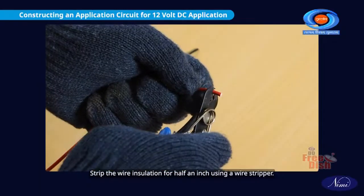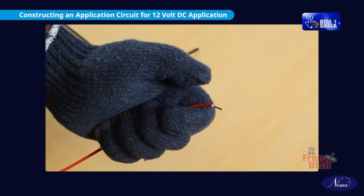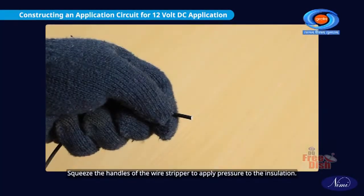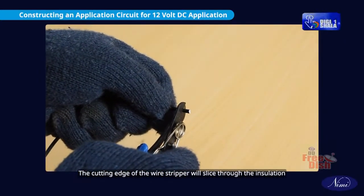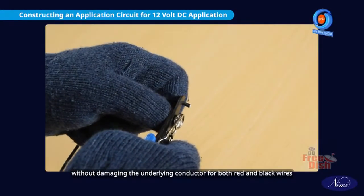Strip the wire insulation for half an inch using a wire stripper. Squeeze the handles of the wire stripper to apply pressure to the insulation. The cutting edge of the wire stripper will slice through the insulation without damaging the underlying conductor, for both red and black wires.